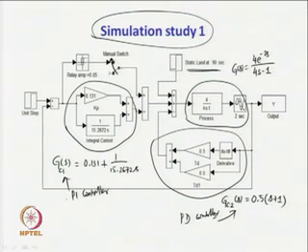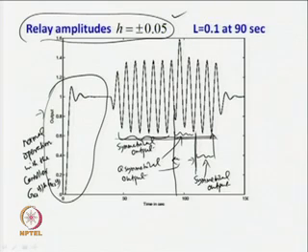And when there is no PI controller during the auto tuning test, we may get asymmetrical limit cycle output. Please keep in mind, only in the presence of the PI controller in the loop, when the auto tuning test is carried out, is the limit cycle signal restored, or we get the correct form of limit cycle output. Now, the measurements can be made from the stable limit cycle output.